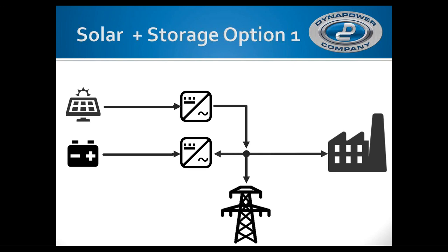At the end of the day, I'll frame this as a bounding condition: you want your battery inverter to be at least the size of your load. Perhaps to state the obvious, if you undersize your battery inverter smaller than the load in anticipation of having the PV there to help carry the load, of course you're relying on an intermittent resource.